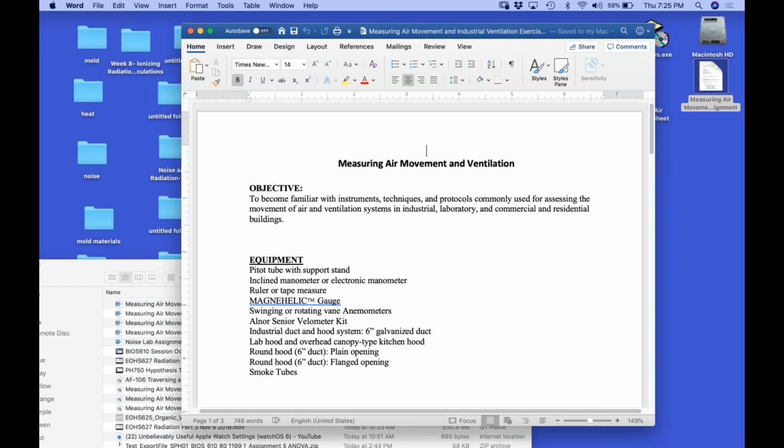Marking this so that you know at each point that the first reading at the top should only be a little bit down, close to the top. The second reading will refer to that. I'm not going to bother with that. I'm just going to do 6 readings, but I think it's approximately right. But really, we should be doing it right, according to the percentages of 6 inches that are in that chart. Because we want equal area surface.